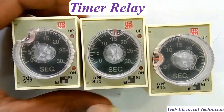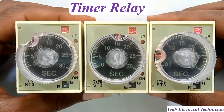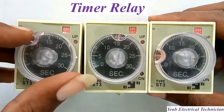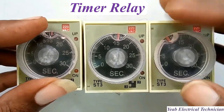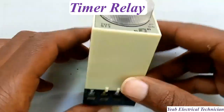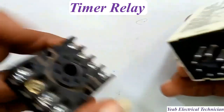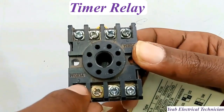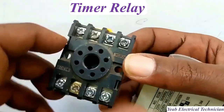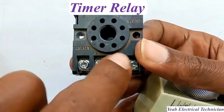A timer relay is an electrical device that controls the switching of a circuit based on a set time delay. It combines an electrical relay with the control circuit to automate tasks by turning a circuit on or off after a specific interval, which can be initiated by a signal or when a power source is applied. These devices are used in many applications for tasks like starting motors, turning on lights, and synchronizing operations.